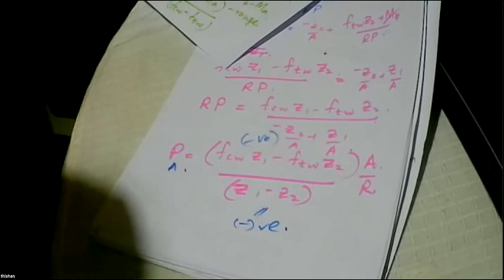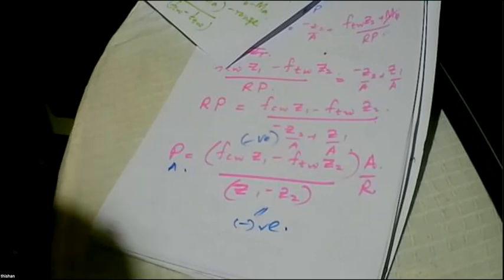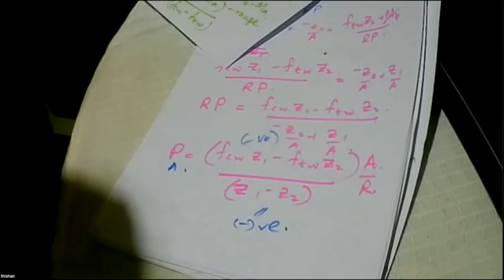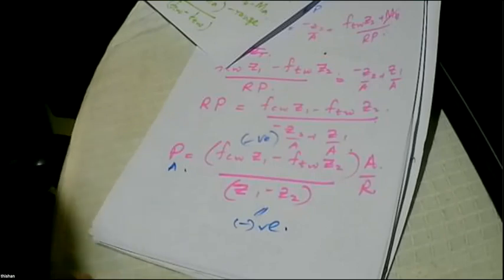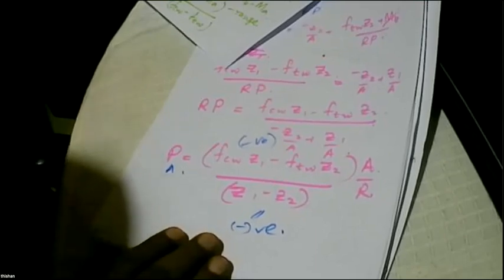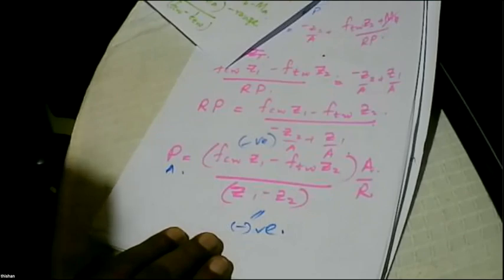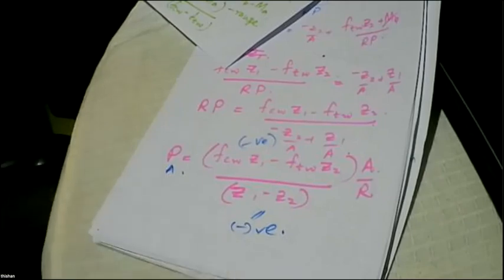So because of that reason, we include all these equations in a spreadsheet, and then we use the spreadsheet for our calculations rather than doing manual calculations. So that's how pre-stressed concrete bridges are designed these days. You can easily prepare a spreadsheet in the way that you like, and then get the computer to do all the calculations. But because you know the equation that you have used, you have full control of the process.